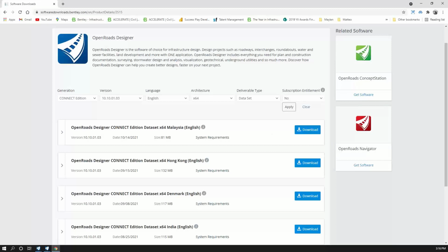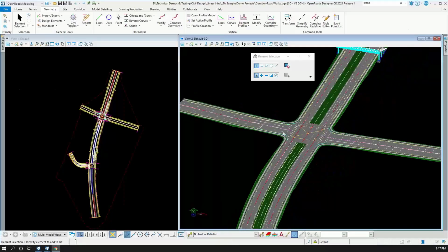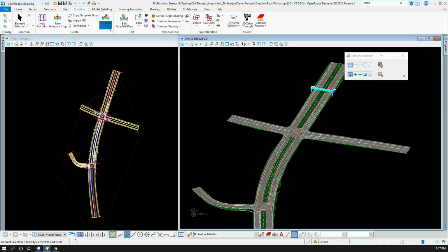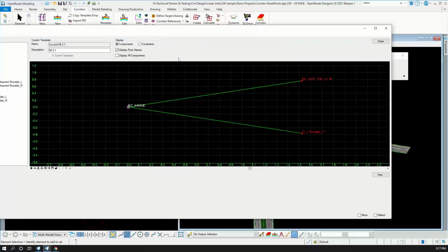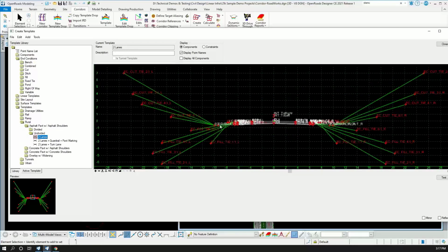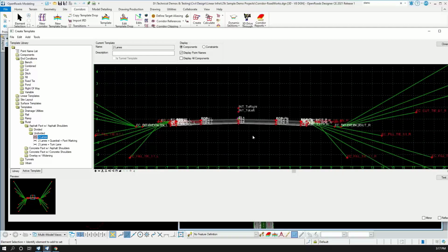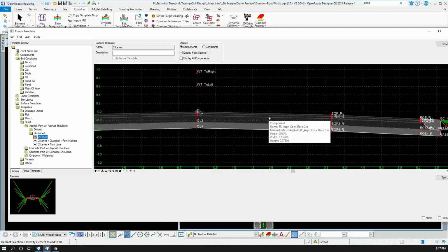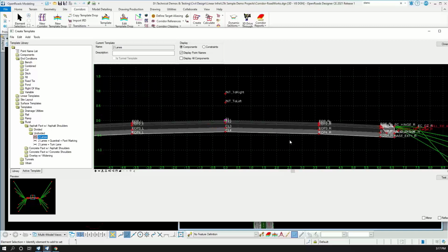Can this be used for a runway project? Yeah, because if you go back to the concept of the template, a runway is basically also like a road. So all you need to do is customize a bit of your template to depict that runway, and then you should be having some geometries that the template would follow. Maybe your template would be wider than this, and the components or the pavements would be a bit different. But yeah, it can be used, sir.